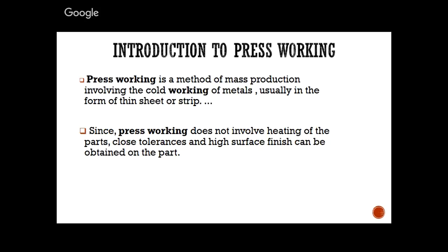Usually these contain thin sheets or strips to give a desired shape. Since press working does not involve any heating process, we can achieve close tolerance and a high surface finish, which can be obtained by using this press working machine.